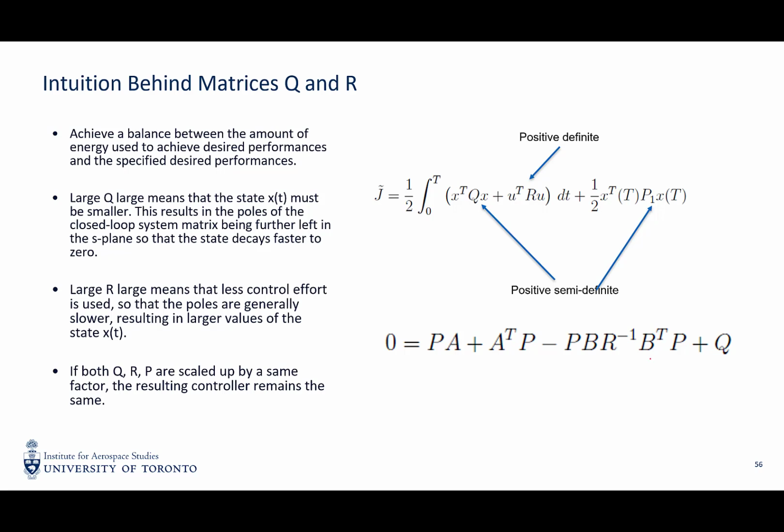Now the thing is that we kind of circumvent the tuning of Kp, Kd, Ki gains in PID, but right now we have some other issues of picking Q and R. We also need to pick something in order to let this work. But then how do we pick Q and R such that the system has a desirable performance?